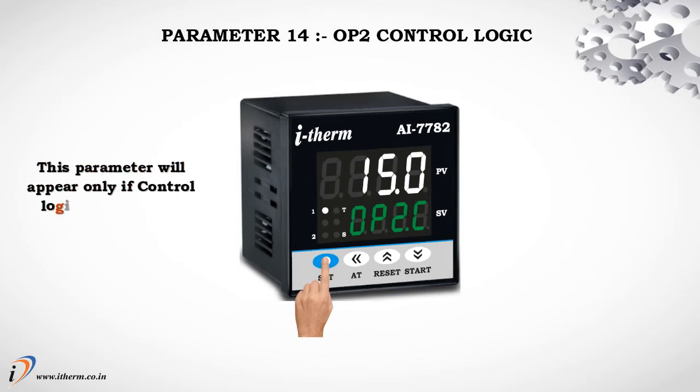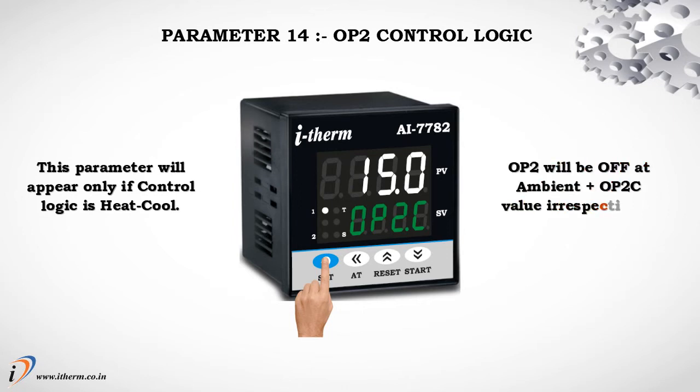Parameter 14, Output 2 control logic. This parameter will appear only if control logic is heat-cool. Output 2 will be off at ambient plus output 2 control value, irrespective of output 2 mode.